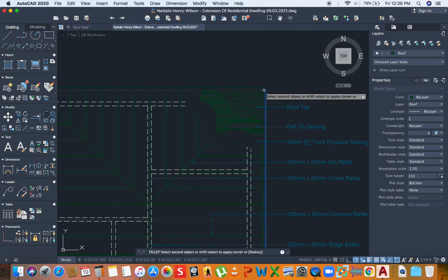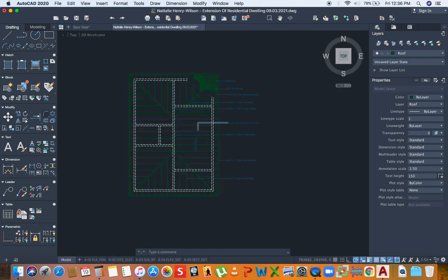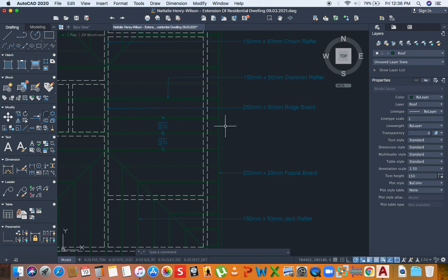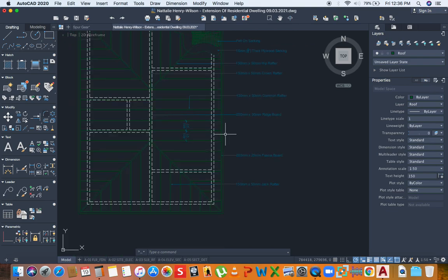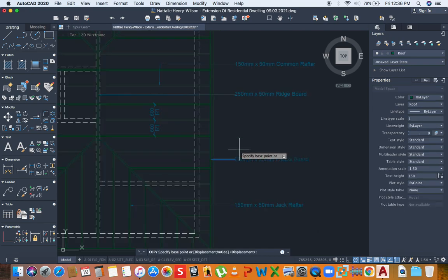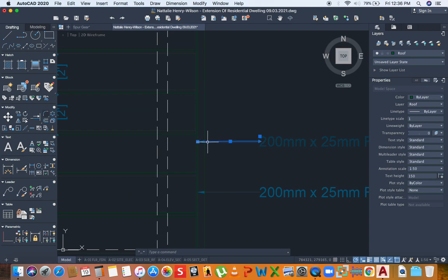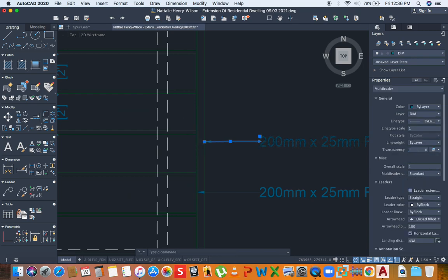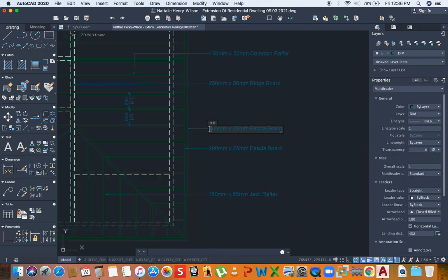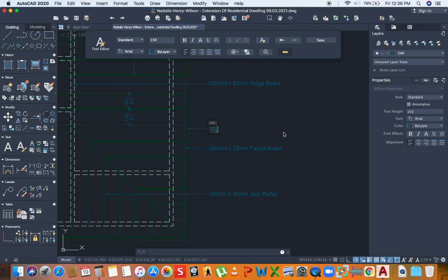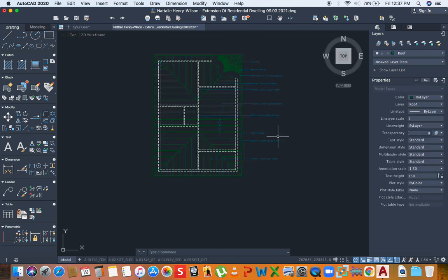And in this case, the gutter goes all around the building based on the fact that the water will flow in 4 directions. So I'm going to copy and I'm going to paste, because I'm going to now indicate the gutter. And 100 millimeters is the thickness of this gutter, or the diameter of the gutter pipes. Right, so that is the gutter.